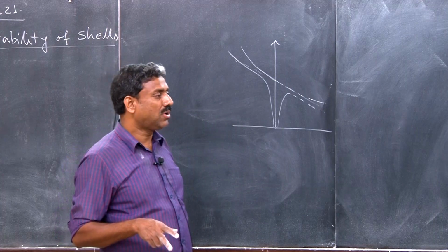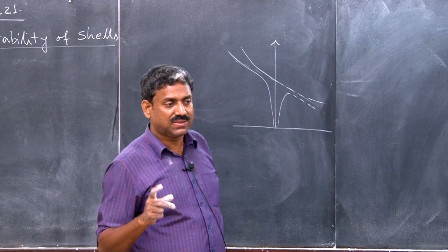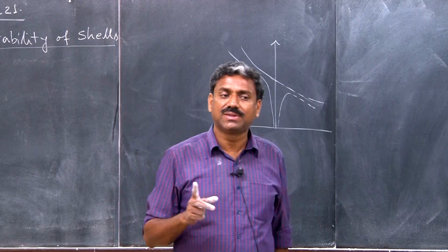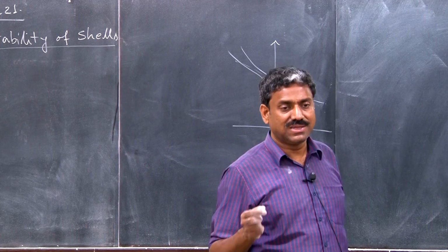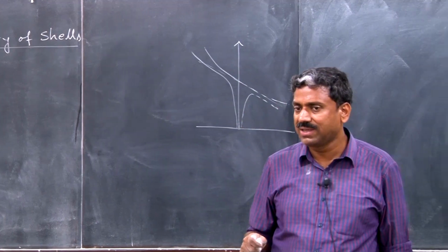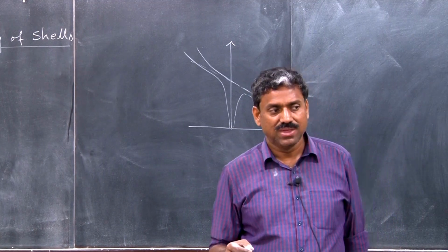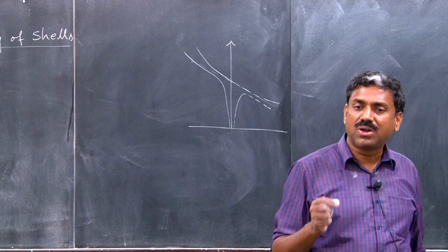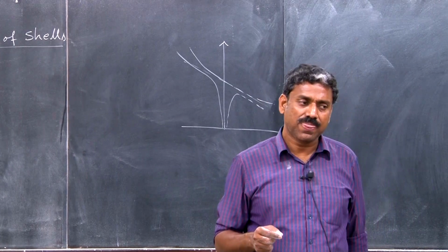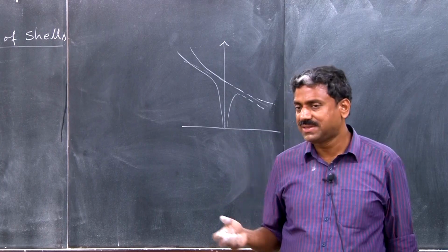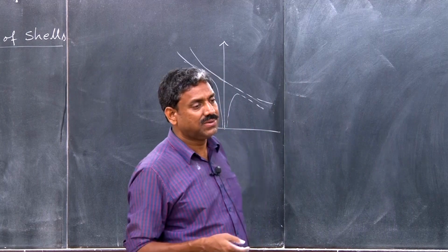There are three important things to incorporate for shell buckling. One is pre-buckling nonlinearity. Unlike others, well before buckling, there is huge nonlinearity in the system. You have to take pre-buckling nonlinearity into account, and you have to consider modal interaction because of geometric nonlinearity. All these things have a cascading effect on reducing the load.